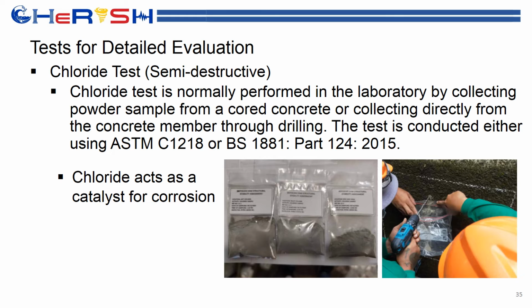Chloride really only happens due to possible application of icing salt, okay, which of course in the Philippines we don't have, or it can be present as a natural component in an aggregate. Okay, so overall, I would say that the chloride issues in terms of concrete here in the Philippines are not really that much in comparison to carbonation.